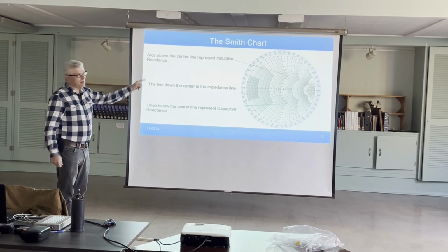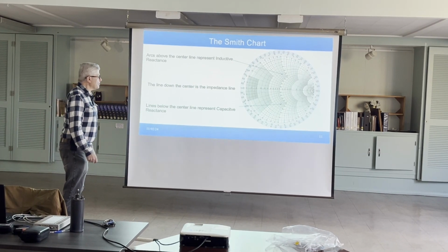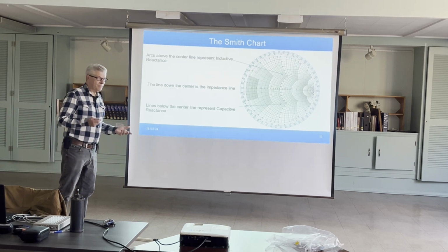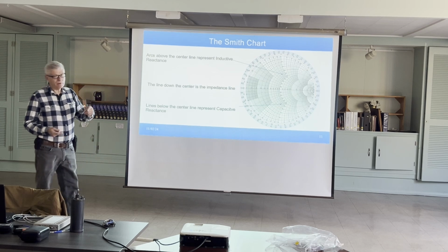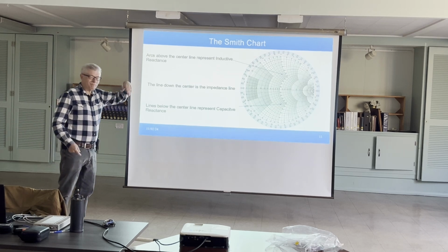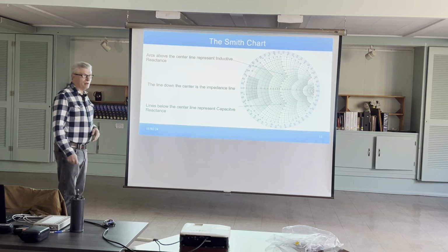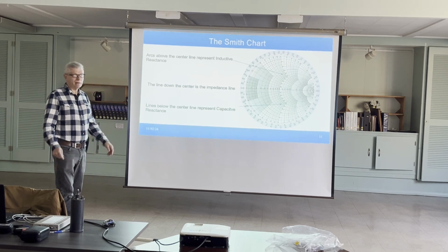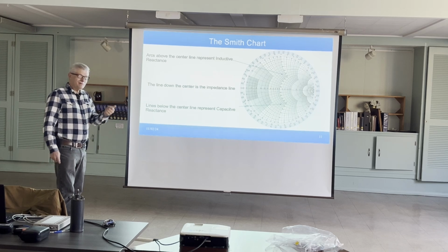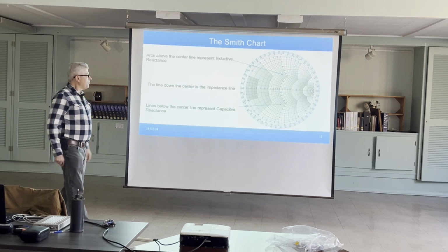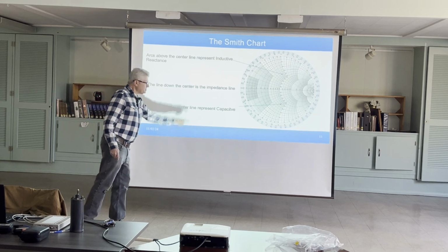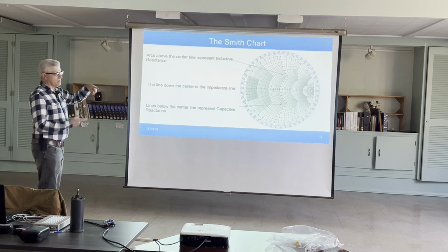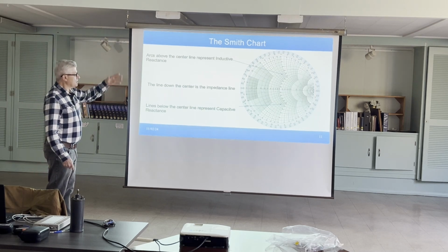But that's one of the things you can use a Smith chart for, and this is for coax or open wire feed. You can do stub tuning with either. I've made stubs, coaxial stubs, to make notch filters out of them to get rid of an annoying signal, back in the days when cable television used to have signals that would radiate out of the cable system right in the middle of the 2-meter band, and your scanner would stop on them, and it would be nice to notch those out. So you make a simple quarter wave open stub to do that. But what the Smith chart allows you to do is to determine where on the line that stub needs to be and the length of the stub, so that you can notch out or match the impedance.